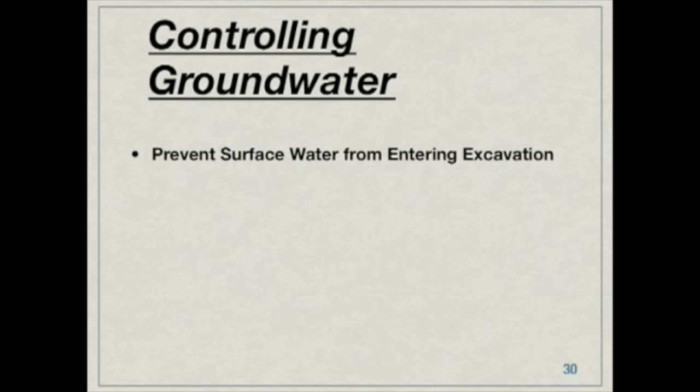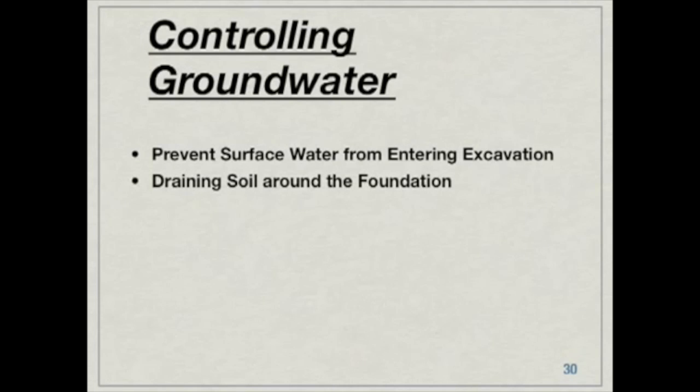And finally, last couple of slides here. We cannot talk about foundation work, whether it be shallow foundations or deep foundations, without talking about the battle against groundwater. Groundwater is going to be an issue when you are doing foundation work, and two of the best ways to remove groundwater are either through sump systems or wellpoint systems.